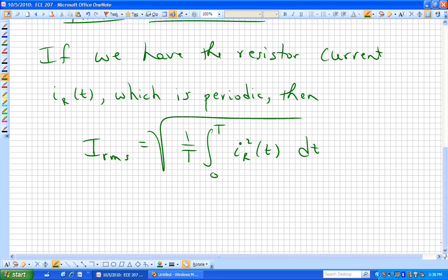If we now have the RMS value of the current going through that resistor, it's easy to compute the average power. Structurally now, that looks just like what you're used to seeing for DC type waveforms, which is I squared R. It's just now that I represents the RMS current value. We square that, multiply by R, and that gives us now the average power absorbed by that resistor.